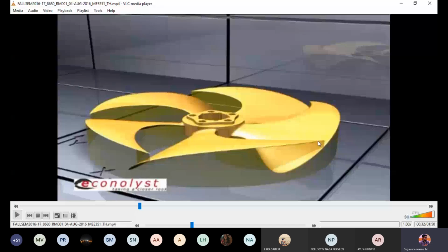You can see between the turbine blade and the table, there is a light yellow region. This yellow region is nothing but a support required for printing this part at this orientation. If I change the orientation, then I may require different types of support, a different volume of support. The amount of support structure will depend on both the geometry of the part and the orientation.